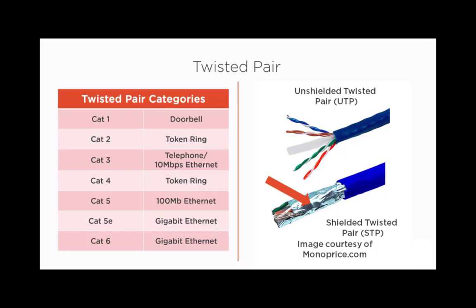When we have large interference, for example if we lay down our wires in a place where high voltage also runs alongside our wires, like in factories or in hospitals where the power supplies also run with our data cable, the induction or interference on our data increases greatly. To overcome this problem, we use the shielded twisted pair cable.